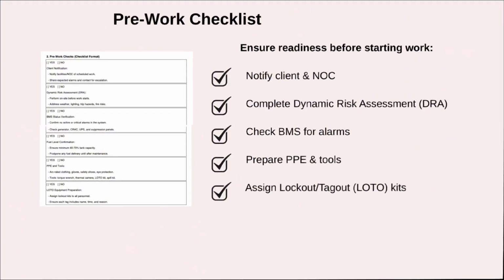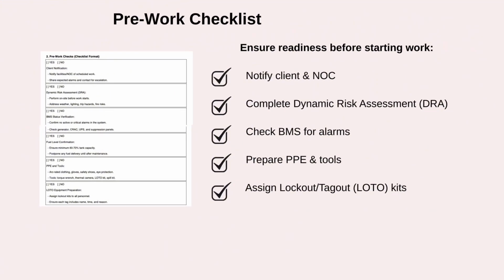Let's zoom into the first critical piece, the pre-work checklist. Before anyone picks up a tool, your MOP should walk the team through a proper prep checklist. Let's say we're about to do a 12-month service on a standby generator. Here's what you do, and more importantly, why. Notify the NOC, Network Operations Center. The NOC oversees live systems across the site. If you isolate a power source or trigger an alarm, they're the first ones to see it. Giving them a heads-up prevents panic and avoids unnecessary incident escalations. It also lets them monitor the system in real time while you're working.